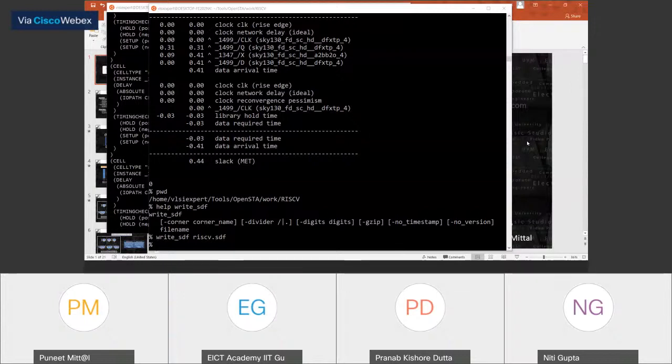So we can use those values, those numbers, back in the synthesis. Like, initially I considered everything as zero. Now the delay value is at 10. Now you're going to reuse those values and run the synthesis so that the synthesis tool optimizes the netlist on the basis of the delay numbers which you have provided.